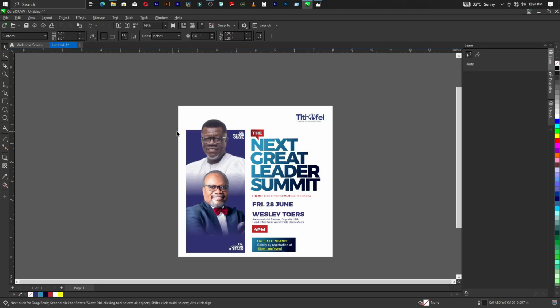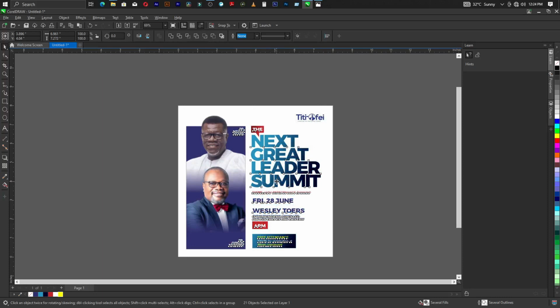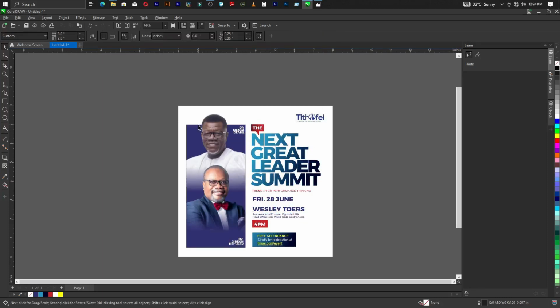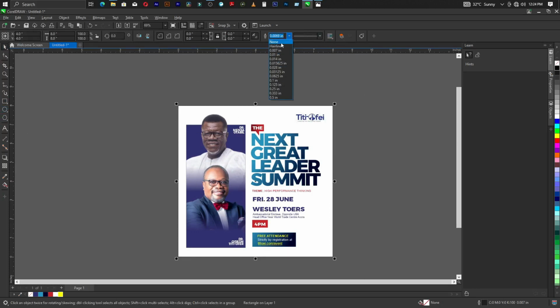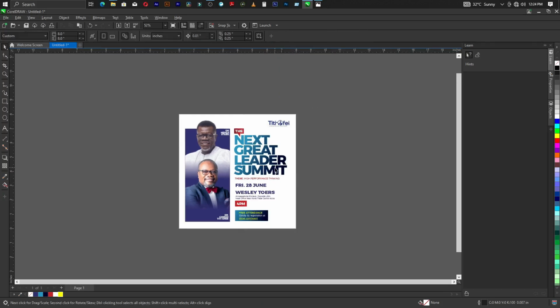So now let's give our design a background. We don't have a background. We just do it on the page we created, right? Okay. Let me adjust it well. I select all and I do it like this. So now let's give it a background. Double click on this tool here. It will give you an outline around the whole page. Okay. Click on the pick tool. Take out the black outline around the whole page. Now let's save it.